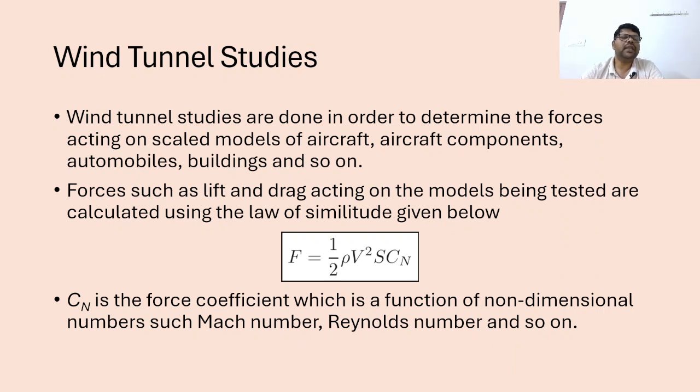Next, in fundamental studies, basically we use scaled models of aircraft components, automobiles, buildings, and so on to determine the forces exerted by the flow on these scaled models. These forces, such as lift and drag forces acting on the model, can be calculated using the law of similitude.